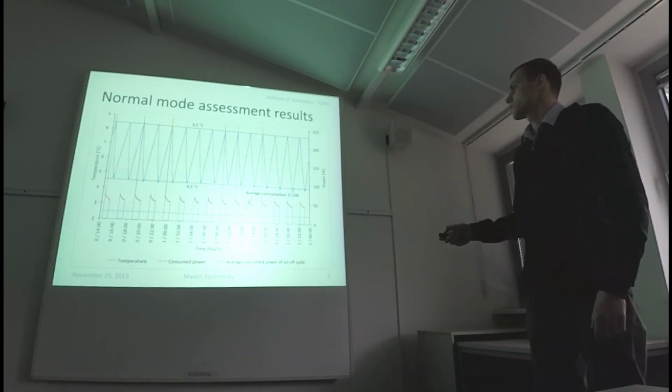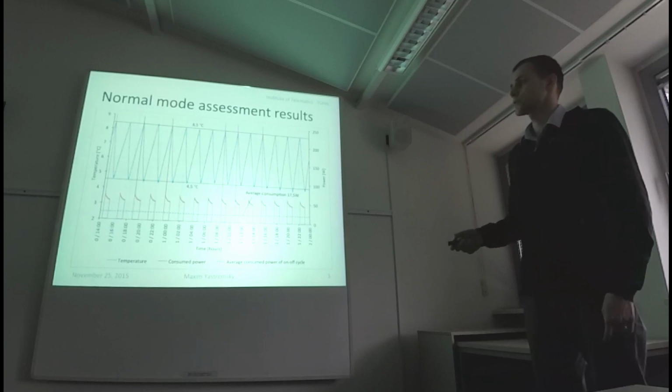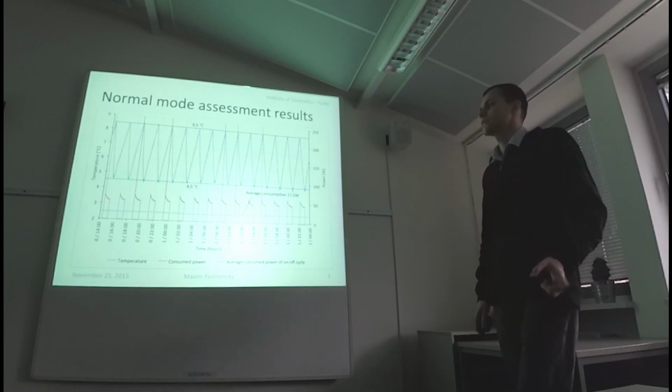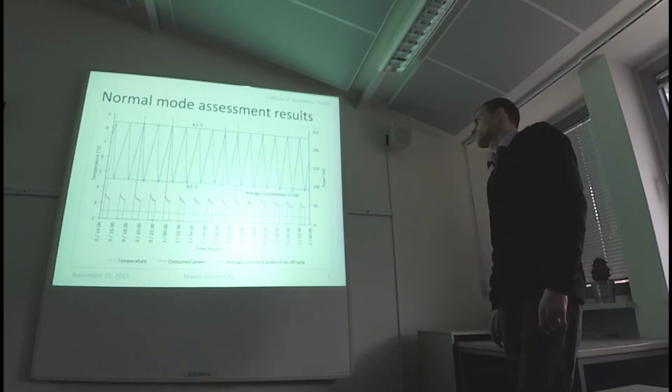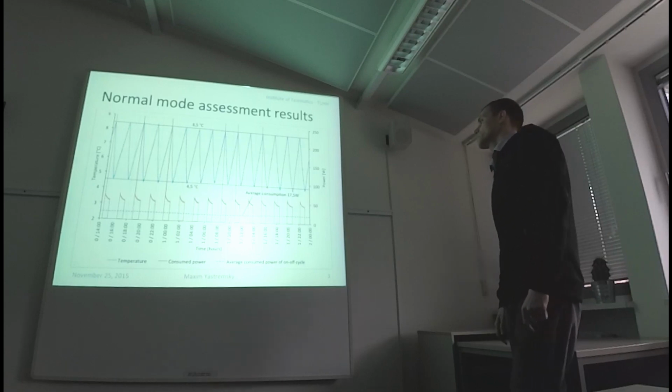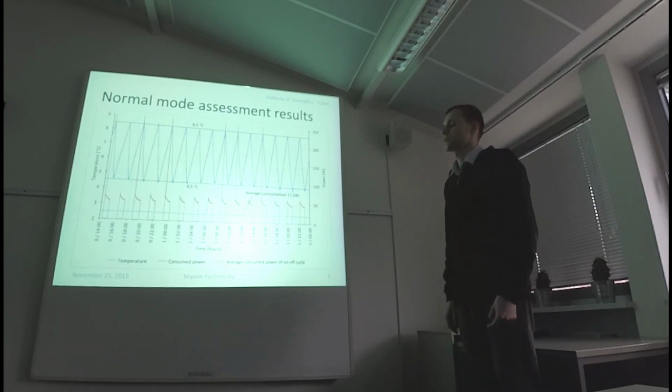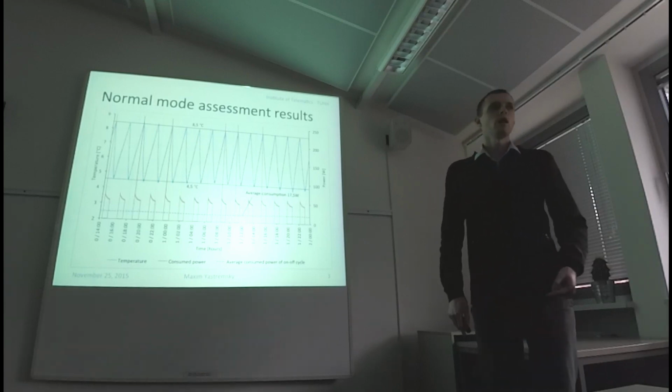The red cycles are power consumption cycles, and the dashed blue line is the average power consumption calculated based on every on-off cycle. The average power consumption of the refrigerator in level 3 is 17.5 watts. This level was used as a base level for comparison with other approaches.